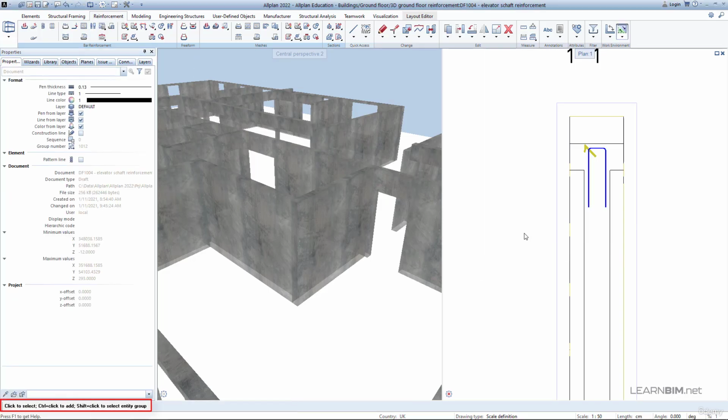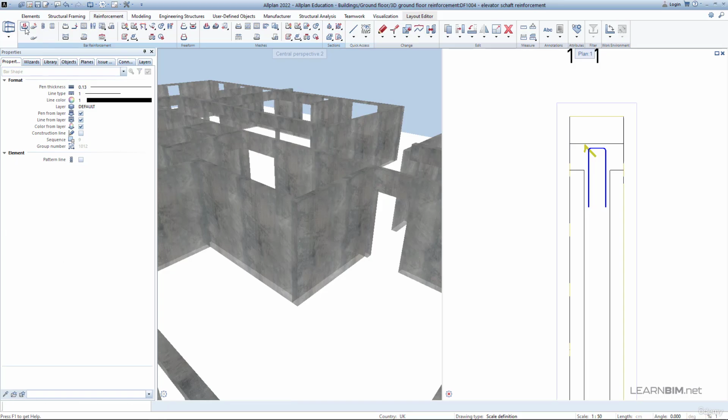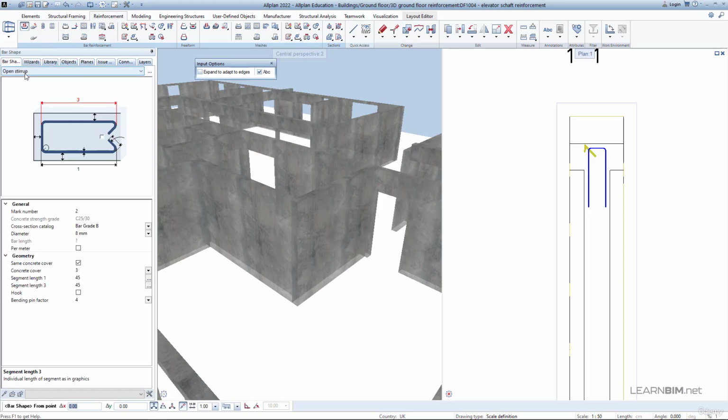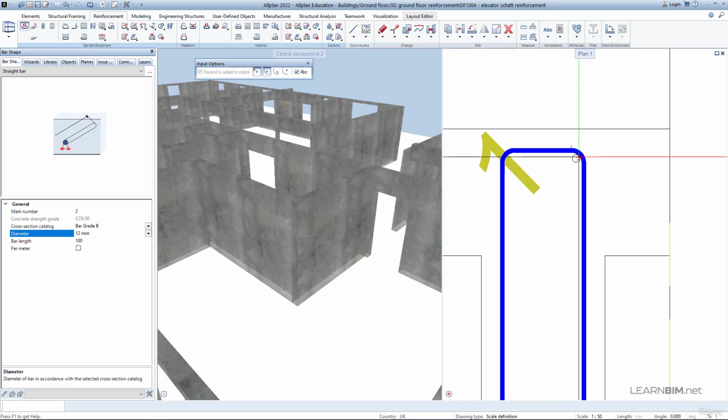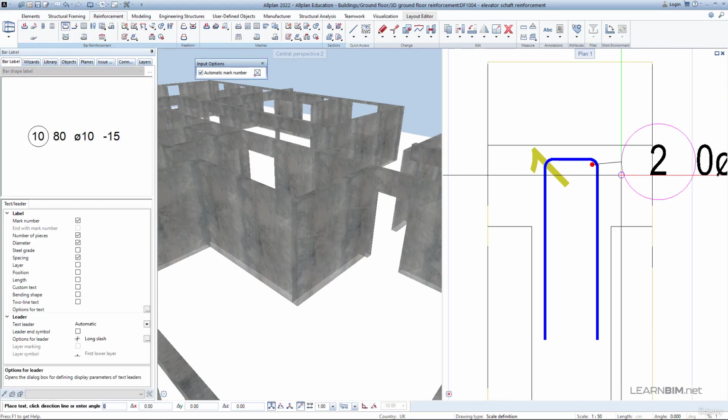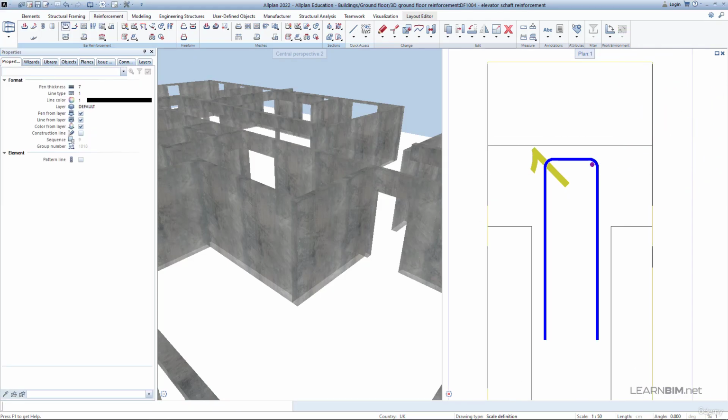command line is shown. Again, go to the Bar Shape command and choose the straight bar type. In the input option window, you have the option to input the straight bar as a point. Only the straight bar has this option. Here you can choose the exact fitting of the point: bar in fillet, place bar at start of fillet, or custom placement. Place the first bar as a point in fillet. And press the escape key several times to exit all the following steps.